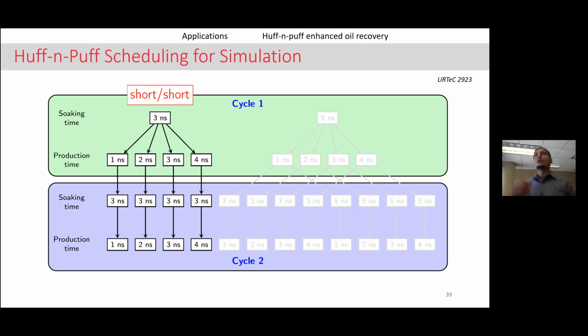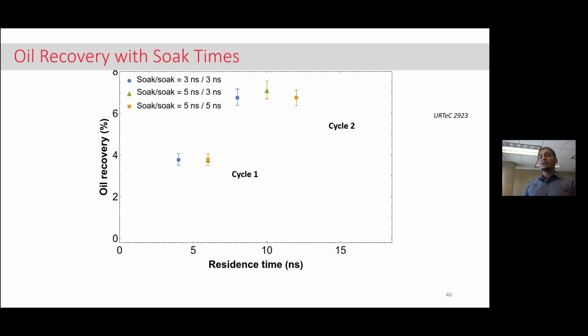Typically in the field, we're talking about 1 month of injection, maybe 2 to 3 weeks of soaking, and then followed by another month of production. And typically you would follow that sequence over and over again. So the question is, why is it 2 or 3 weeks of soaking? And why is it 1 month of injection? Why can't it be 2 months of soaking and then perhaps 1 month of injection? And you can design experiments that would do exactly that. And I think I'll skip through that for right now.